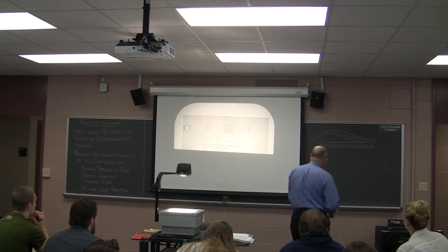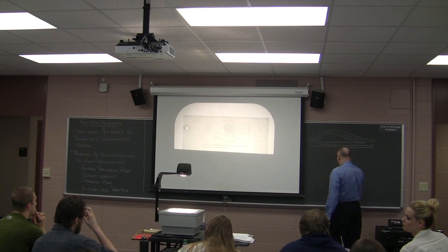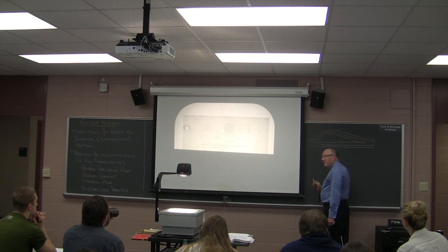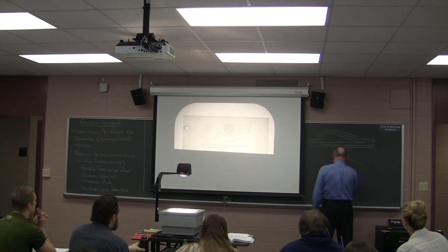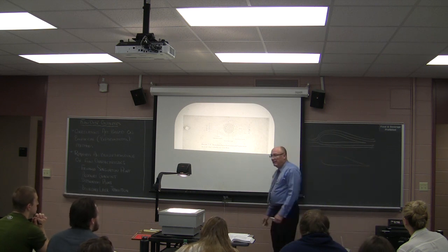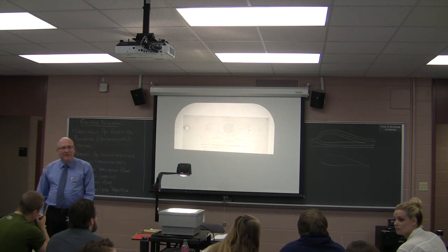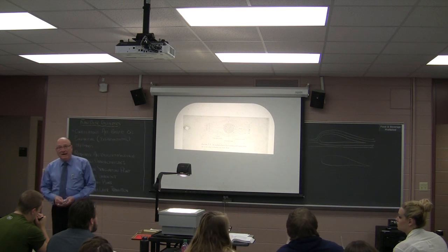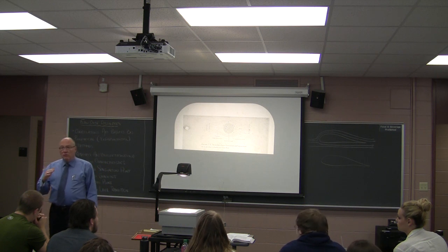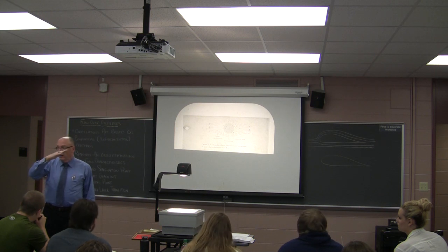Now here's something for you. Why can airplanes fly upside down then? Why do some airplanes have symmetric wings? But then one side's not longer than the other. What about a wing like this? Okay, symmetric wing. What do we do? What do you have to do to have a symmetric wing fly, Austin? You need angle of attack. That's right. You need a different angle of attack. An asymmetric wing can have a zero angle of attack and be fine. But with the symmetric wing, you need some angle of attack. So in other words, you've got to tip the wing so that it's cutting into the air.